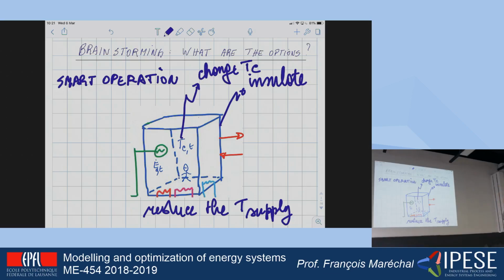So perhaps you just have to better use the radiators. You have thermostats, which are supposed to regulate the temperature, and if the temperature is too high, the valve is going to be closed. So officially, to reduce the supply temperature you have to optimize it: have a better knowledge of the radiators in the building and identify the one that has the lowest needed area. Take the valve that is always open and verify that it is open not because the room temperature is too high, but because the radiator is too small. Then you could increase the size of the radiator. Or if none of the radiators is at the bottleneck, then you can reduce the temperature until you find one of the radiators at the bottleneck.